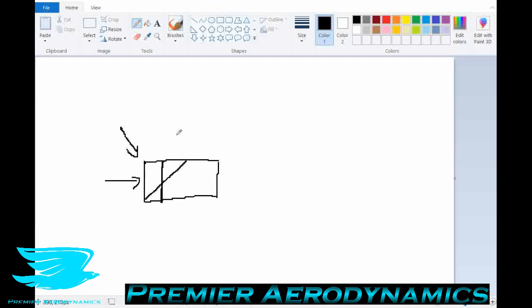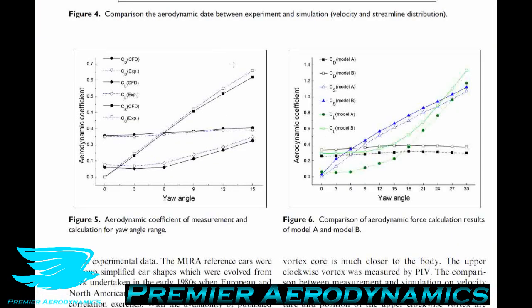So when we have a drag, which equals half times the density times the velocity squared times the area times the drag coefficient, the area is going to be changing. So what I think is that the difference in area should also be taken into account and not just the drag coefficient, because that is kind of a pseudo drag coefficient that we're looking at. We're not really looking at the drag coefficient in particular. We're looking at the changes in drag, which are then decomposed into the cross-sectional area and the drag coefficient, not just the drag coefficient. So I wanted to just go through that first so we get that groundwork out of the way.